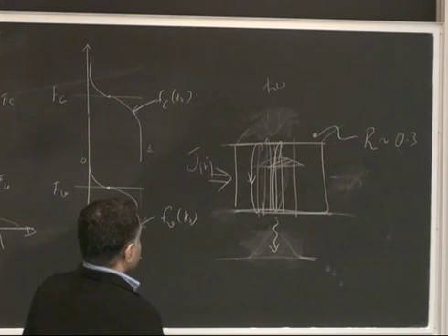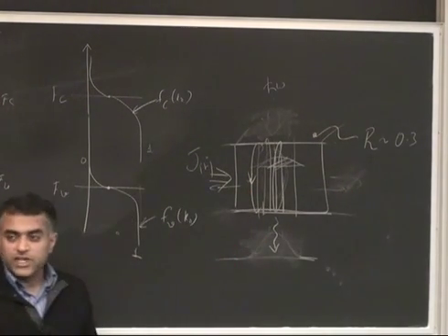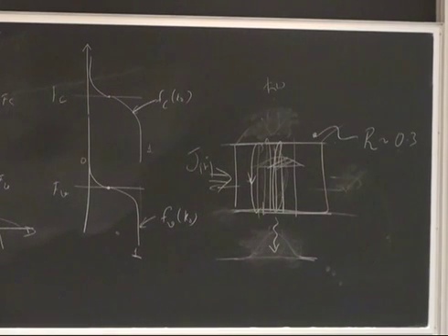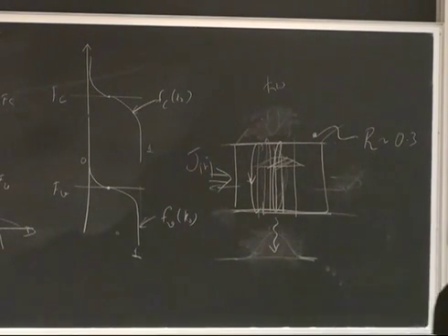The other way is if you want light to come out vertically rather than from the edges. And that would be called a vertical cavity surface emitting laser, or VCSEL, VCSEL, right? Vertical cavity. And I think it's very clear what you need to do there is to put the mirrors on top and bottom and bounce the light back and forth like this, right?